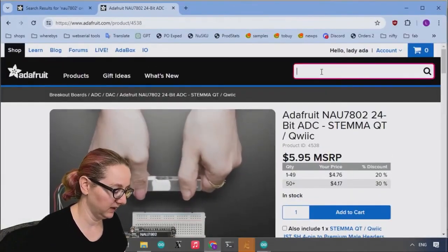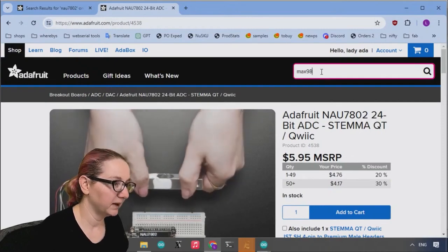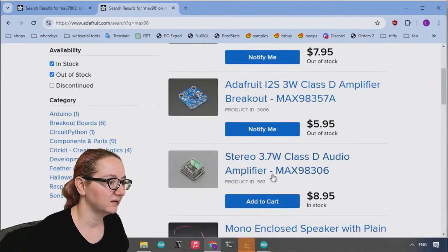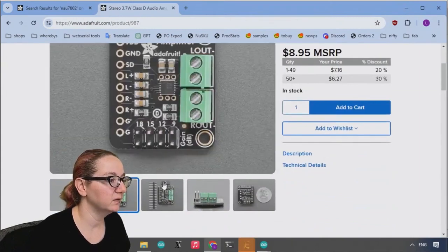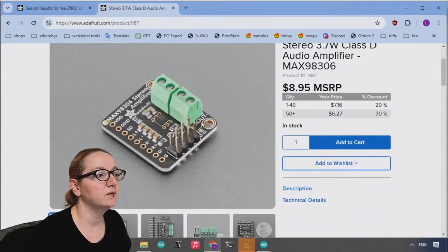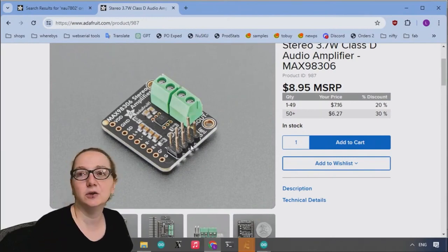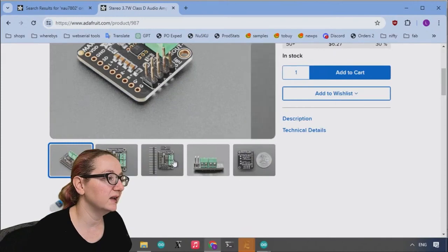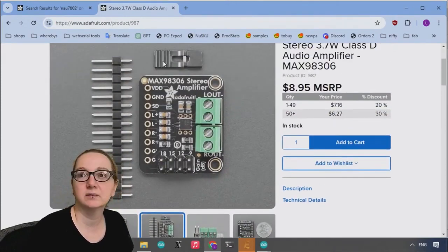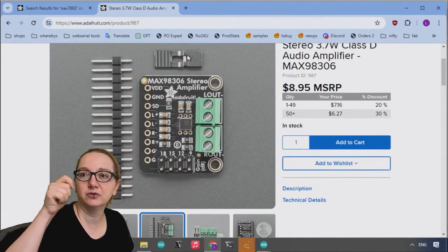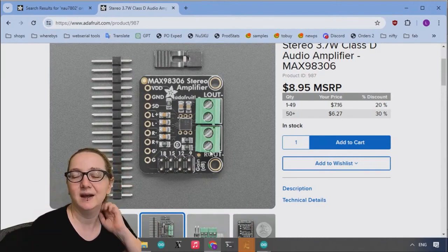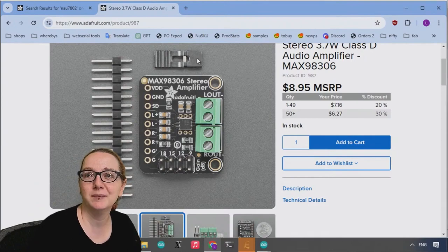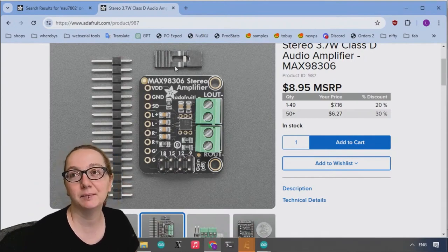So another thing is, on like this MAX98 audio amplifier board, it's hard to see here, you can select a gain. I use a 2x4 male header connector, and then a little handle jumper, and you plug it into what gain you want, 9, 12, 15, 18. The problem is a lot of people lose the jumper. I mean, this is very inexpensive, and it can pass high current.